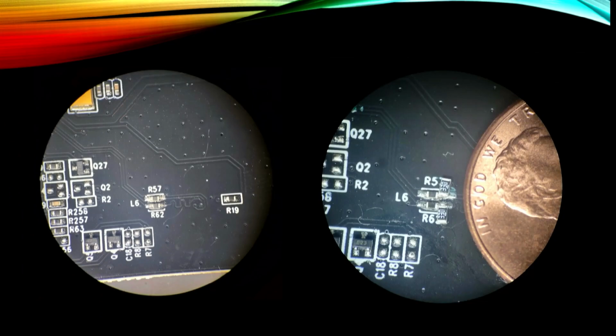So the vendor says you need to put a 20 to 40 ohm resistor in there. So the best way to do that was, let's just wire it onto the board. So I went ahead and I soldered in. So this is the bus here, and it had 2 resistors in line. It was interesting. So I'm looking at that and I'm like, hey, there's 2 resistors in line.